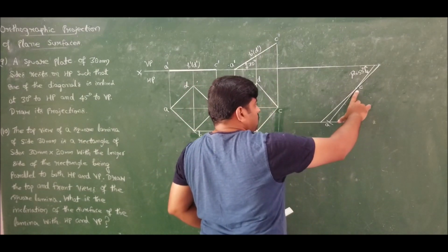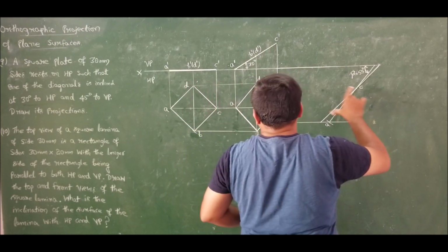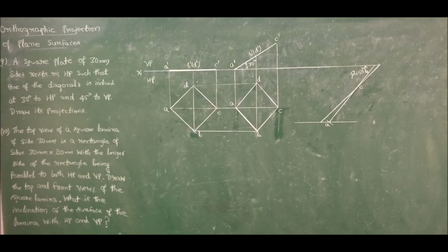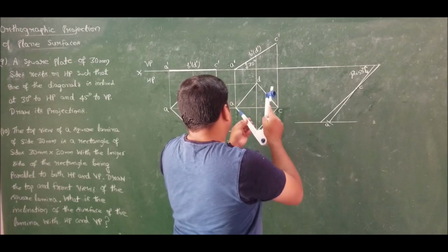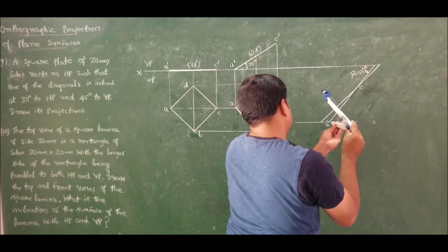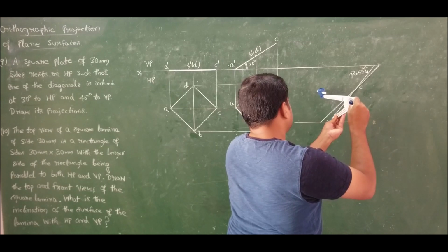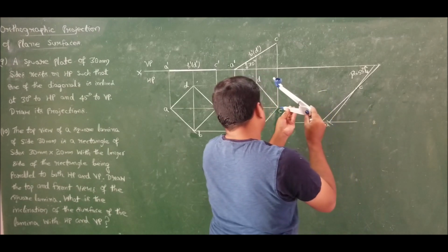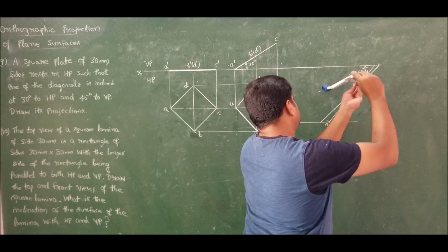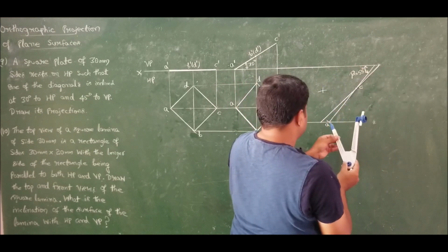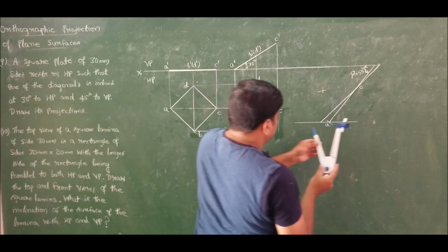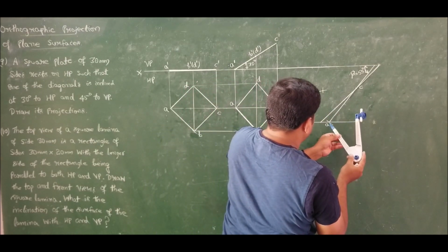Now on the AC beta angle, construct D and B. To do that, let me use a compass. From A you measure D, cut an arc. From C, D is measuring the same length, you intersect this previously drawn arc. Similarly, from A you measure B, draw an arc.